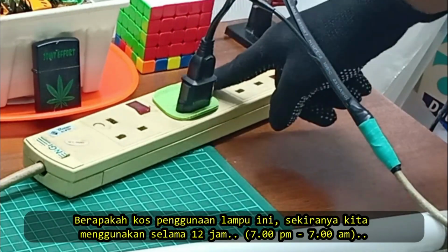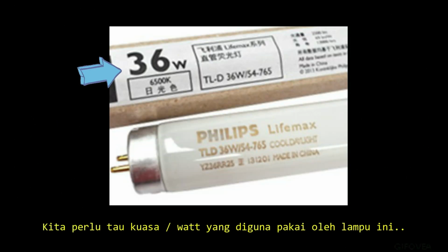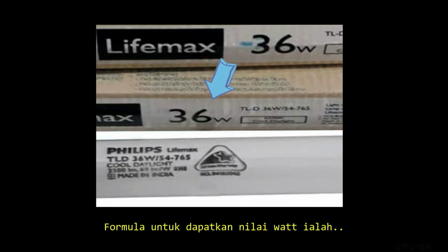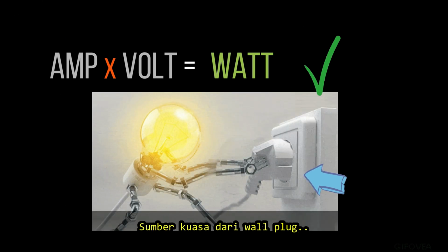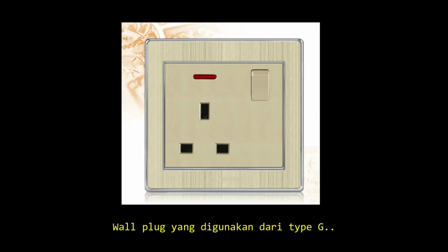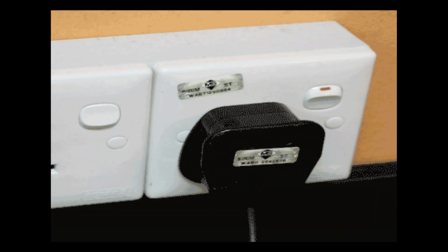How much do fluorescent lights cost using for 12 hours? Let's do some math. First, we must know the power consumption or watt used by this lamp. The formula to get watts is current or amp multiply volt, and we can get the power consumption in watt. Volt here is a power source from the wall plug. In Malaysia, the power plugs and sockets are of type G. The standard voltage here is 240 volts and the standard frequency is 50 Hz.